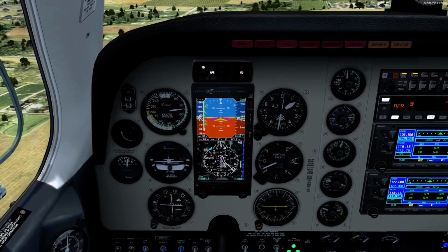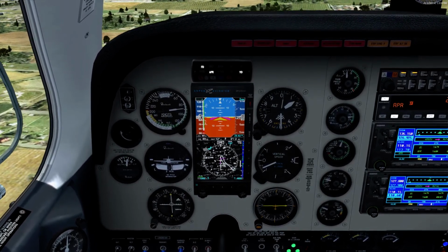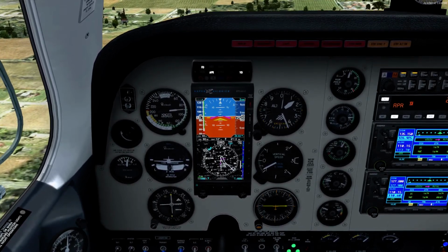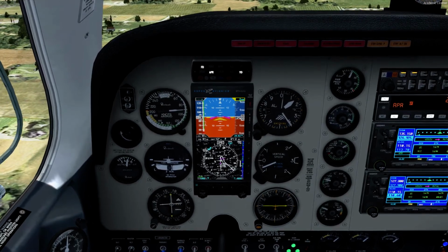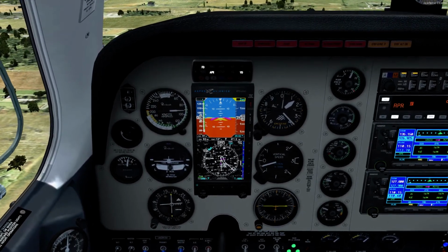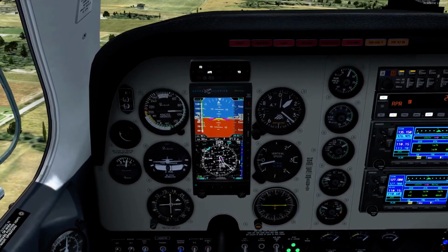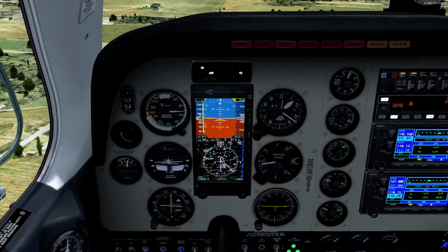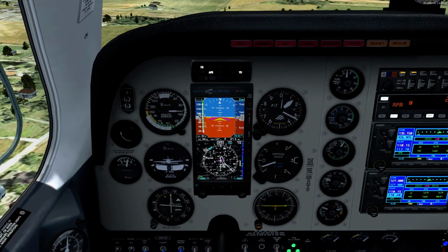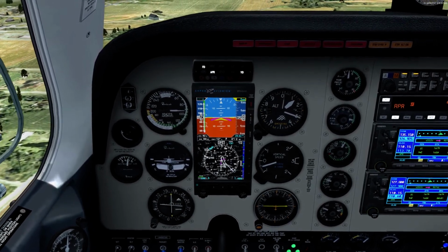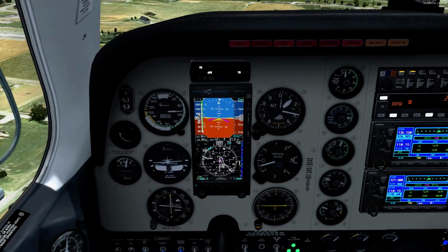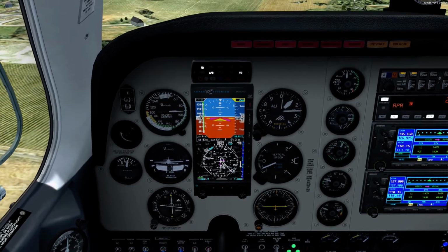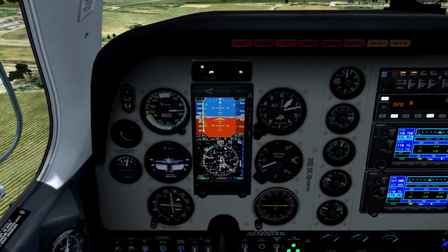And based on our airspeed indicator, we are pretty close to our approach speed, passing through 1,500 feet now. We're going to increase our power a bit. Didn't mean to say bring back. And we're going to turn a few degrees to the left, just to keep on the localizer. We don't want to make big corrections, like I said. We want to make nice, smooth, gentle corrections. So now we're about 400 feet to minimums.